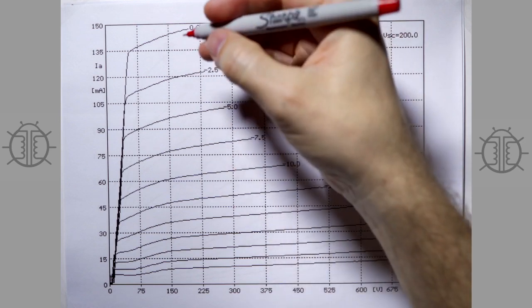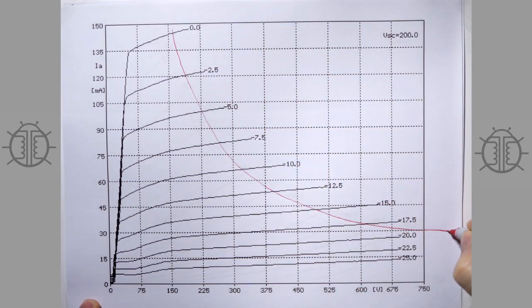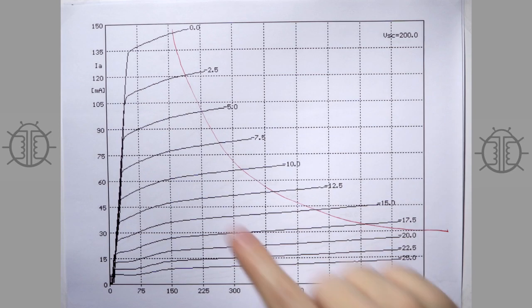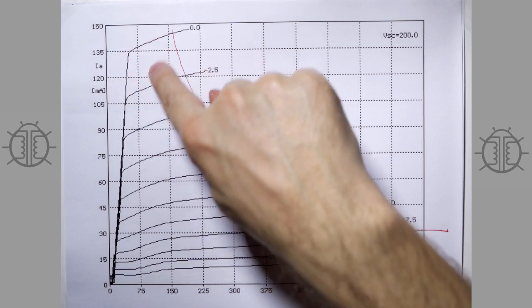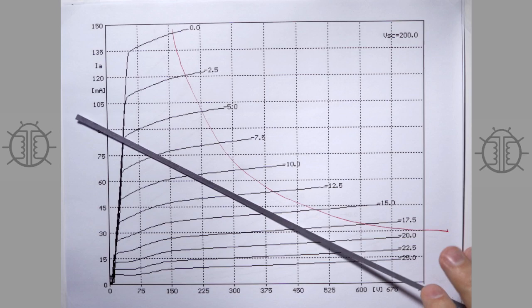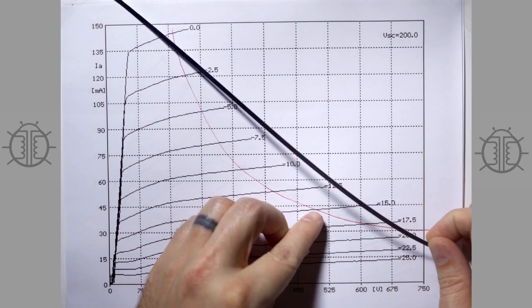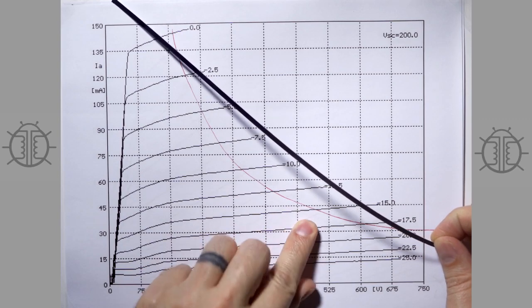So let me just really quick draw our load line again, or I'm sorry, our dissipation line again, looks something like that. That's probably wrong, but you get the idea. You know how to do that now. But you can see, look, now we have access to this area over here we can swing through. So if we're going to do a class AB output stage, we could pick our operating point. I guess we don't want to go above our max for our...